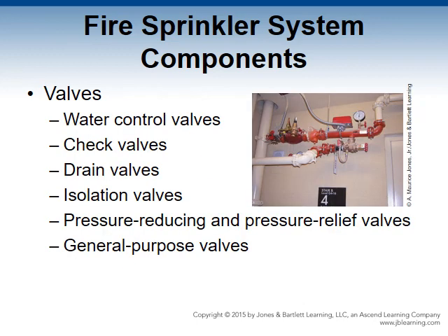Valves. Each of the different types of sprinkler systems use a particular valve design specifically for the system application. Without valves, there would be no way to control the water supply or flow in a sprinkler system. Looking at our water control valves. When open, water control valves permit water to flow into and through the system. When closed, they prevent water flow or isolate parts of the system for service.